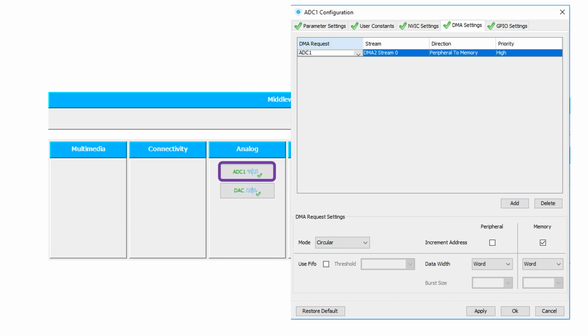In this case, we want our ADC's peripheral data register to write its value, or rather the DMA to take the data from the data register of the ADC, which is a peripheral, and store it in an array which is in memory. So hence we say the direction is peripheral to memory. Let's give it a high priority.